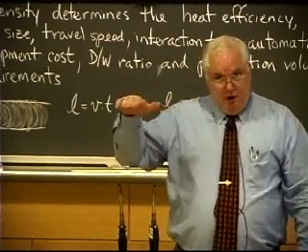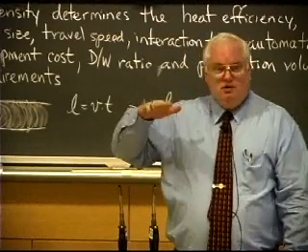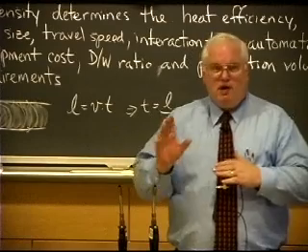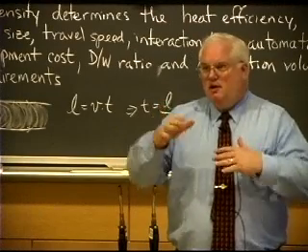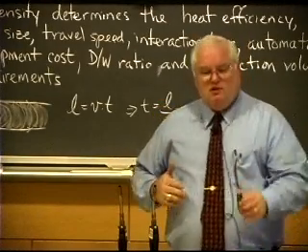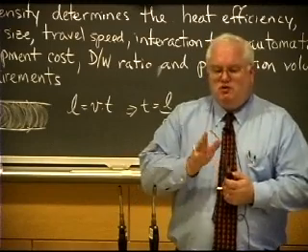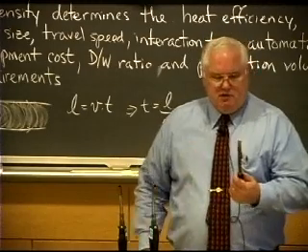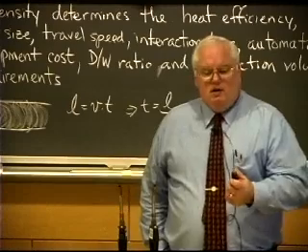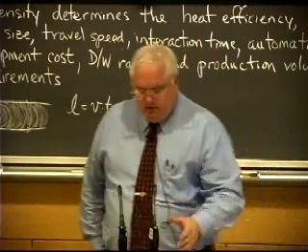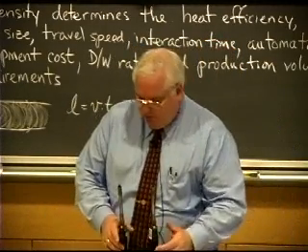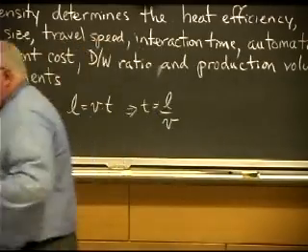If it was a solid monolithic strip and I had different temperatures, it would bend away from the heat source in each case. This thing actually has some residual strain right now because it's still warm, but once it cools down, it still has a little bit of residual bend because over time I bent it too far and it took some plastic set. But it always bends in the same direction because it's based on material properties. So I'm not going to pass around the metal piece, but I'll just pass one around. You can look at the torch. You don't need to play with the MAP gas.